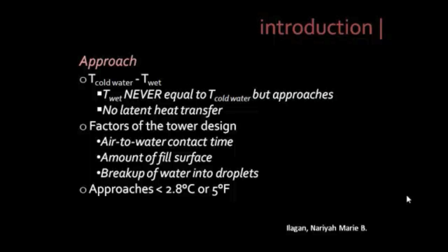This is known as the approach. Its magnitude is dependent on the tower design, which include the air-to-water contact time, amount of filled surface, and breakup of water into droplets. Approaches for cooling towers rarely reach 2.8 degrees Celsius or 5 degrees Fahrenheit.